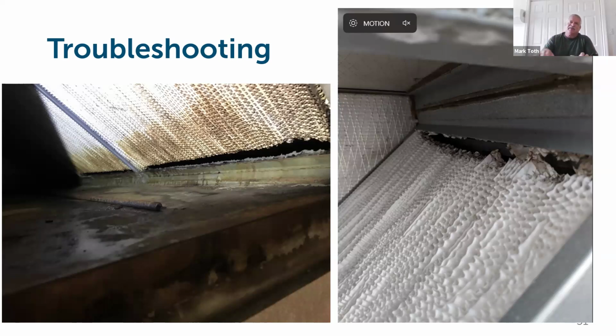You wash the dishes, you put it on the counter. Tomorrow morning you get up, that sponge is shrunk up and it's hard as a rock. That's what will happen to an ERV core if it gets wet. It will shrink and it will get hard and brittle. And now you are not passing air through the core. You're passing it mostly through these open voids in the system. This one here is actually a commercial, multi-core unit that is at a brewery. And the people in the brewery were washing the units out. And this is what happened.